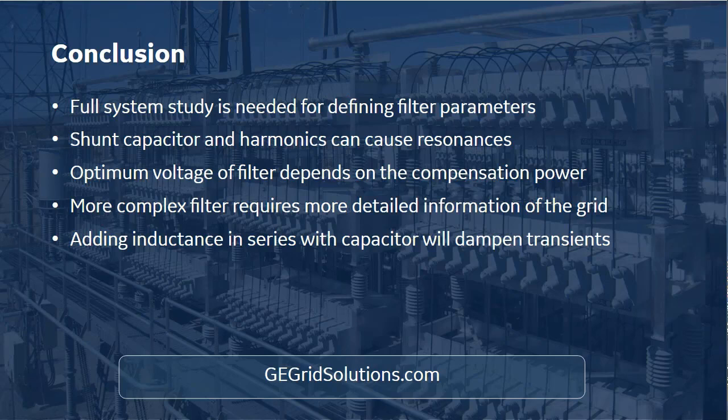So with these 3 banks, you would get steps of 5 megawatt, 10, 15, 20, 25, and 30 megawatt. I would do it like that. And the physical size for one bank is, I would say, roughly from 3 times 5 meters to 3 times 7 meters if it's a single bank. Something like that is the footprint which is required.